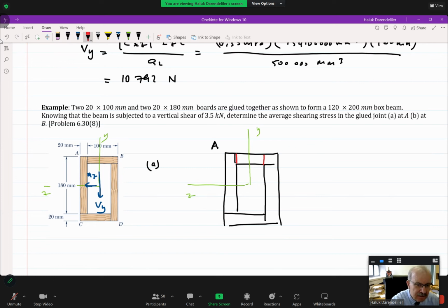Okay. As long as this point is considered, the glued part is here, but it's not important for us, because all these stresses are within the body. And by gluing, we are attaching all the surfaces to each other. So here, now, the area that we should remove is this. It should be symmetric to the stress region or shear flow region that we are referring to. Otherwise, the Q here is different than the Q here, and as a result, stress. Is this clear? So you have to keep symmetry to remove an area to get a correct result.